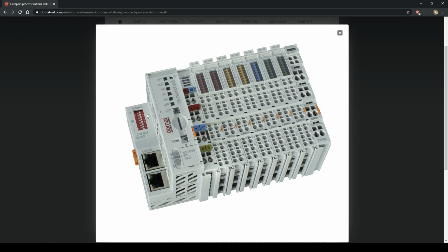If you have a COM version, then there is a 9-pin connection which works in 2 modes: one as RS-232 and the second as RS-485. So it's a communication port. You can use it for Modbus, BACnet, or communication with other devices. If you don't have this version, then there are just these 2 Ethernet ports for communication outside, or you have to buy a communication card.